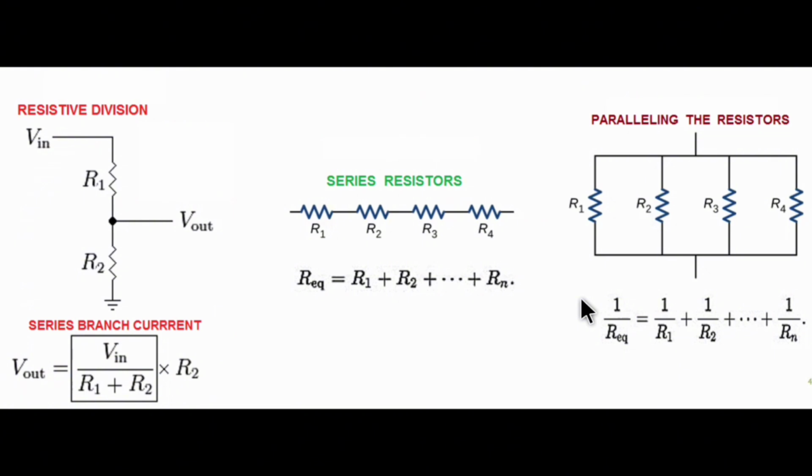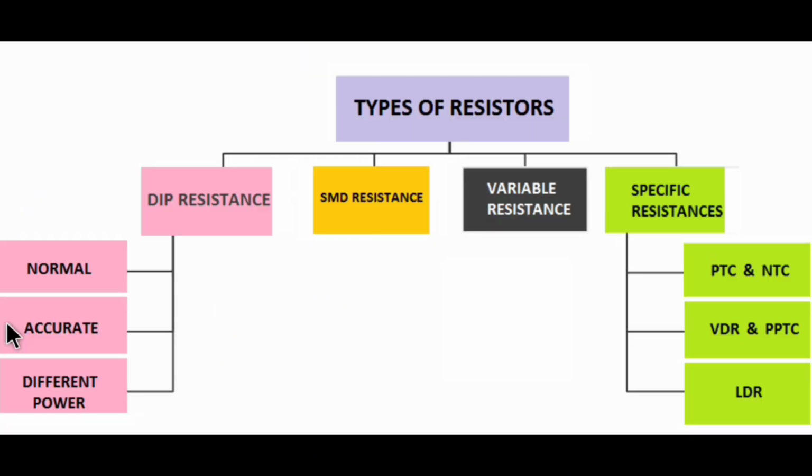Another circuit that we use is the resistance dividing circuit, or voltage divider, where we have a higher voltage level, for example, the input voltage, and we want a lower voltage level. A practical example is, say, 5 volts for the input circuit for an IC or 3.3 volts for our microcontroller. We can build such a circuit. Well, we need to determine this resistance. We want to note that the resistance divider circuit has various applications in electronics that we will get to know over time.